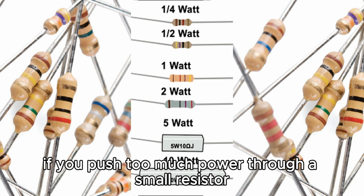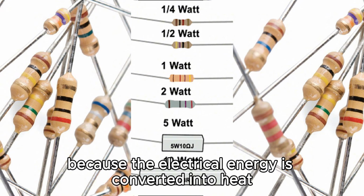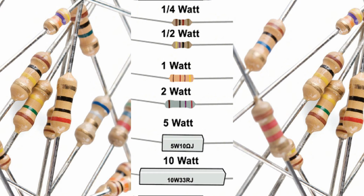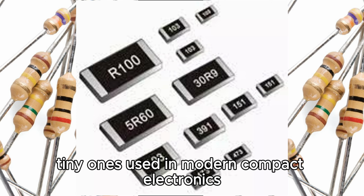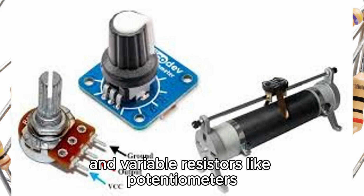If you push too much power through a small resistor, it can literally burn out because the electrical energy is converted into heat. There are also different types of resistors. Through-hole resistors, the classic ones with wire leads. SMD, surface mount device resistors, tiny ones used in modern compact electronics, and variable resistors like potentiometers, which allow you to manually adjust resistance.